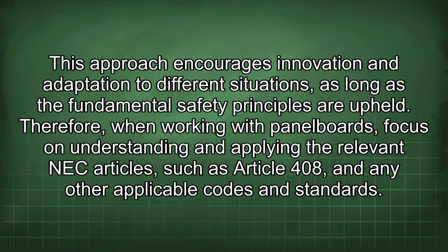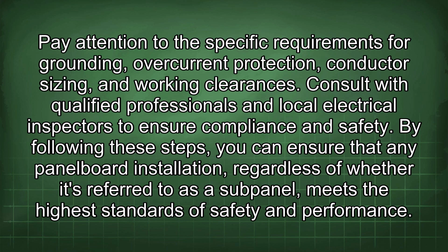Therefore, when working with panel boards, focus on understanding and applying the relevant NEC articles, such as Article 408, and any other applicable codes and standards. Pay attention to the specific requirements for grounding, overcurrent protection, conductor sizing, and working clearances. Consult with qualified professionals and local electrical inspectors to ensure compliance and safety. By following these steps, you can ensure that any panel board installation, regardless of whether it's referred to as a subpanel, meets the highest standards of safety and performance.